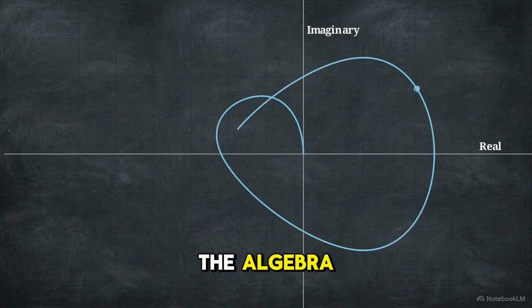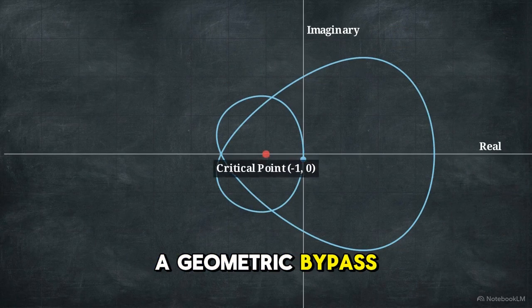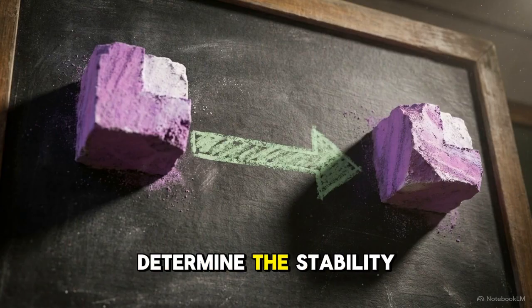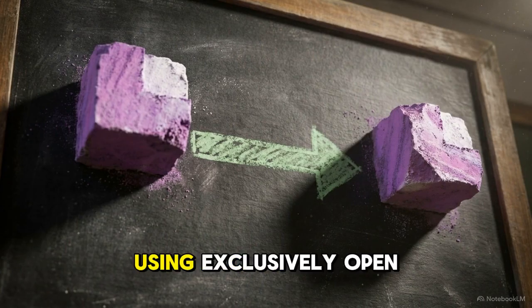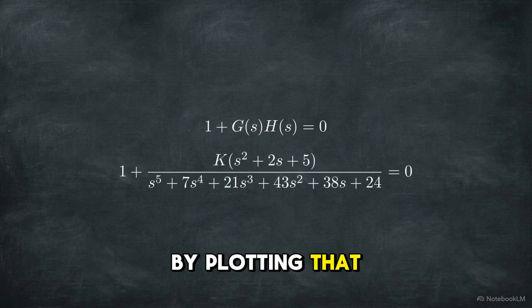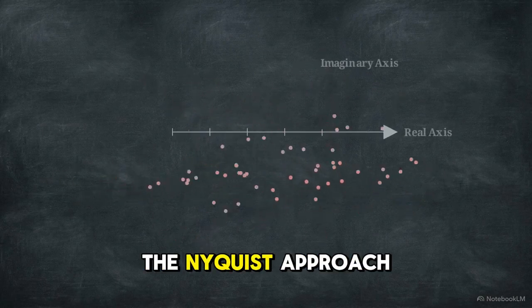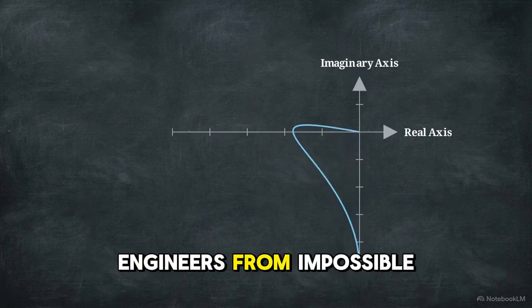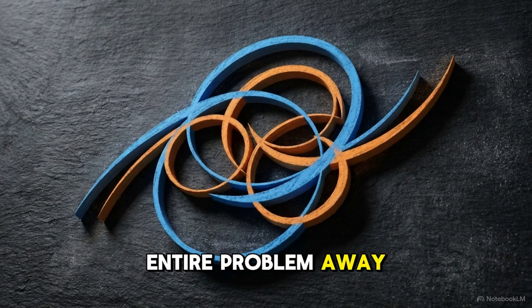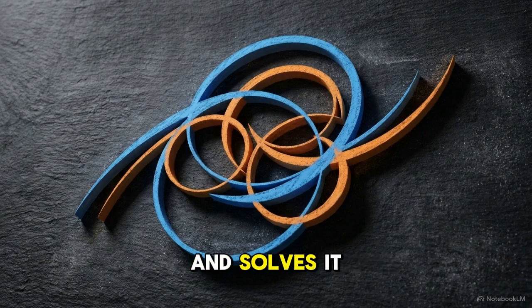Instead of fighting the algebra, we can use a geometric bypass, the Nyquist diagram. This method allows us to determine the stability of a closed-loop system using exclusively open-loop frequency response data. By plotting that open-loop data, the Nyquist approach saves engineers from impossible factoring. It shifts the entire problem away from complex algebra and solves it purely through visual geometry.